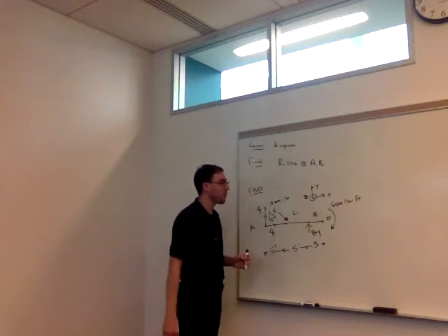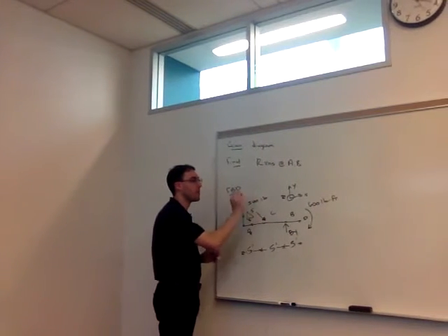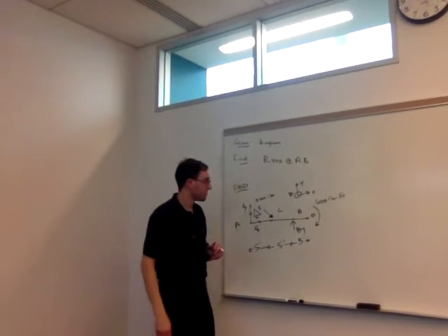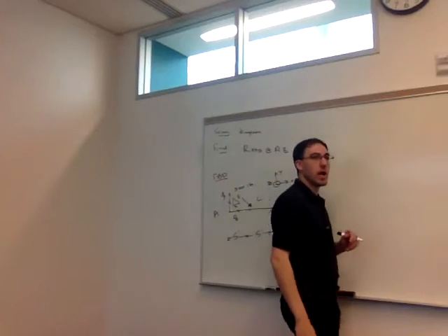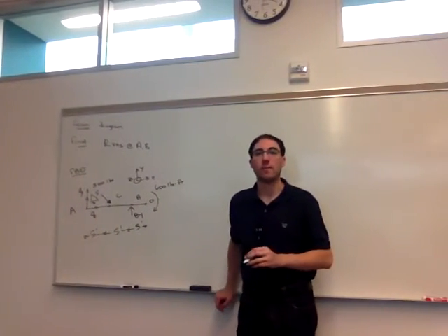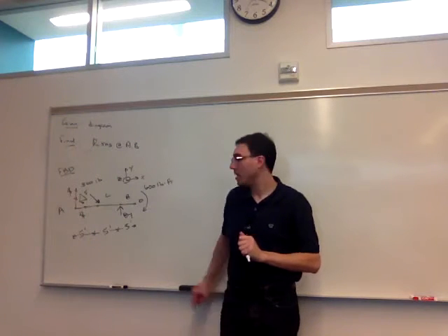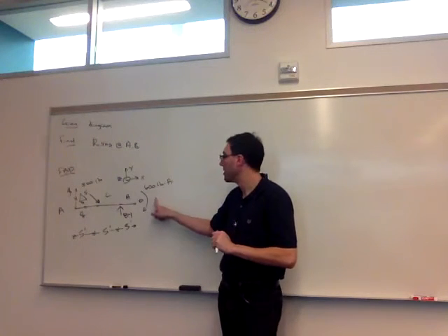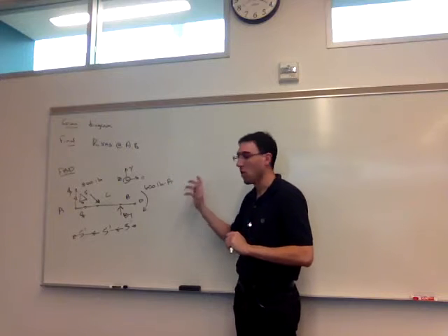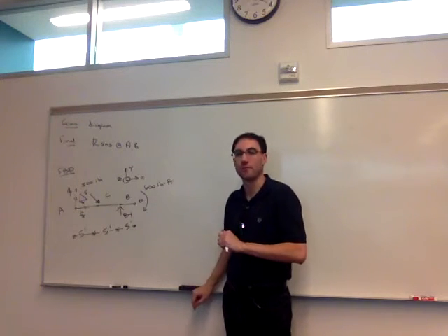We have those applied forces. Everything's labeled, and we have a coordinate system here. Any questions about the free body diagram? Do we show a couple on the diagram or not? Yeah, so here's the couple, 600 pound-feet. So couples or applied moments have to be included on your free body diagram.